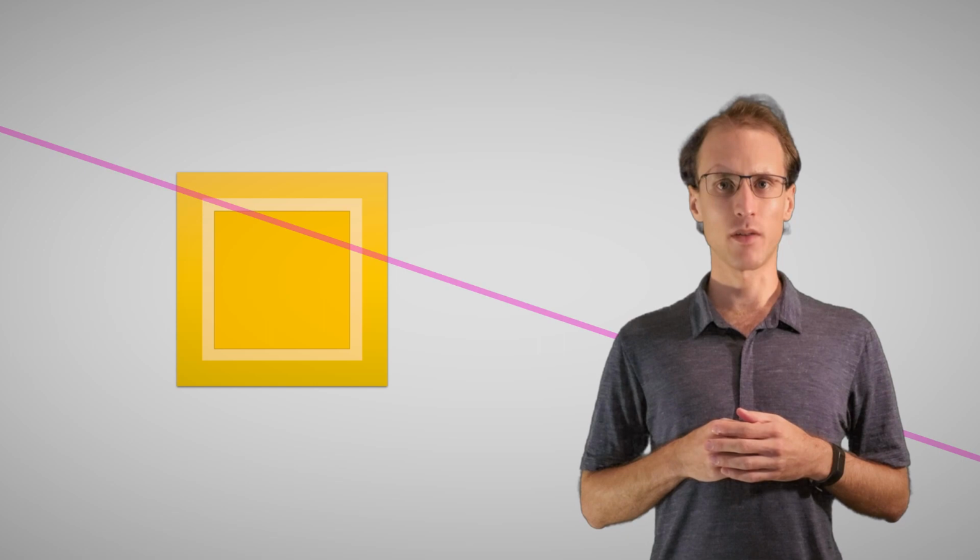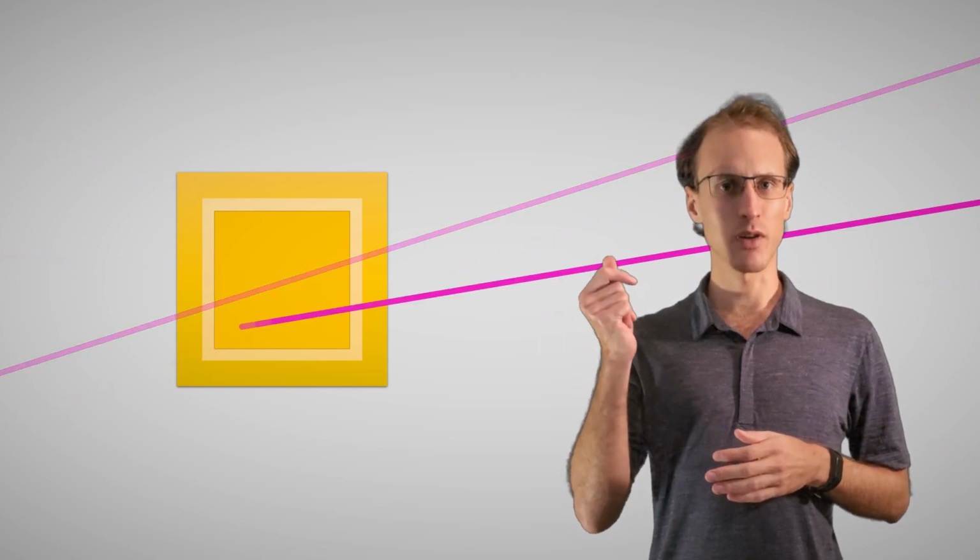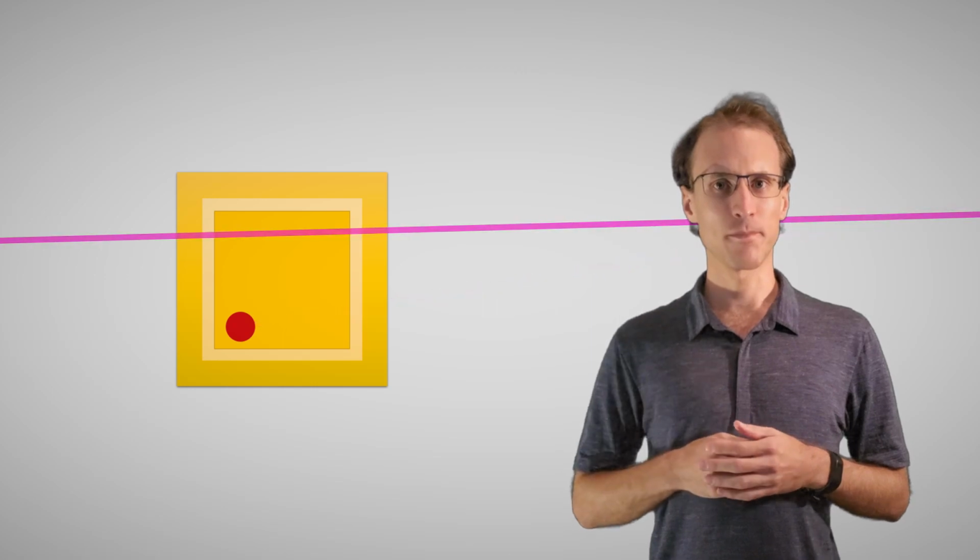Thus, it is the job of the gravitational reference sensor to house and isolate the test masses from the surprisingly noisy solar environment. Unfortunately, there is one source of noise that does not particularly care about our feeble attempts of shielding: high-energy particle radiation. When a high-energy particle originating from the Sun or cosmic rays impacts the dense gold-platinum test mass, it has a chance to be stopped, depending on its energy. As these particles are mostly positively charged protons, this creates an average net positive charge rate.